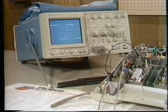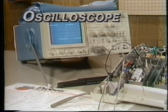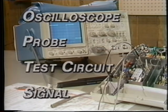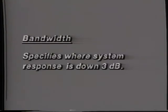To understand how to select a probe, we need to consider the entire measurement system. We need to examine the oscilloscope specifications, the probe specifications, the test circuit itself, and the signal characteristics. Now, I'm sure you're well acquainted with scope specifications: input capacitance, input resistance, and bandwidth. But how do they define measurement accuracy? Well, take bandwidth, for example. It specifies where the system response is down 3 dB, or to 0.707 of the initial amplitude.